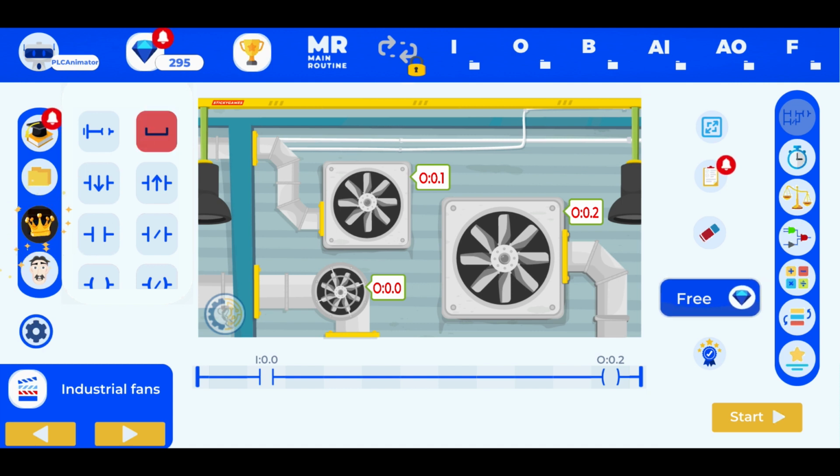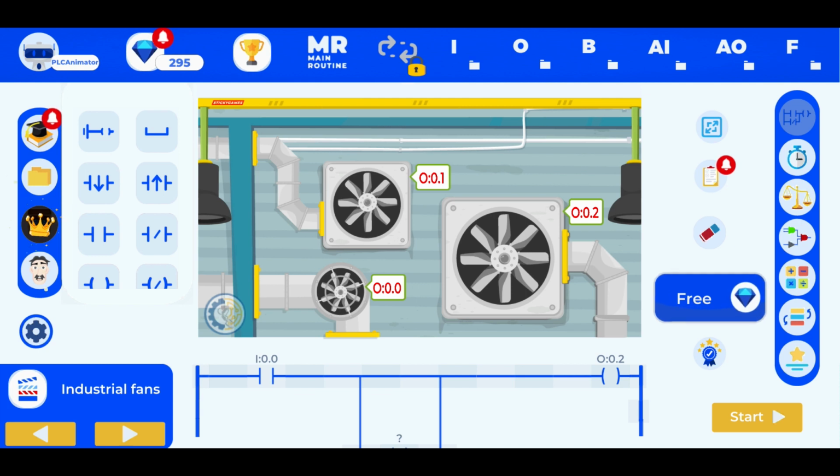So for our software, when we select that instruction and insert it in an empty space, automatically it's going to be established by our programming and sent to the upper part in the center of our ladder language programming. So therefore, this instruction, we're going to move it within. We can eliminate it momentarily.